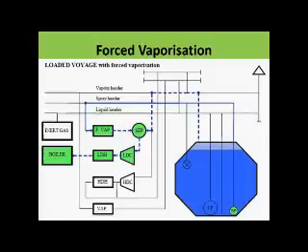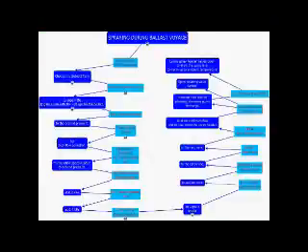I will show you on different ships on these simulators. This is the spraying during the ballast voyage. We can take the liquid from the tank. You have seen that, and of course, when we throw the liquid back into the tank through the spray nozzles, and when it is spraying, it is automatically converting to gas, or at least vapor. That will have a mixture of liquid and gas, and we suck those.